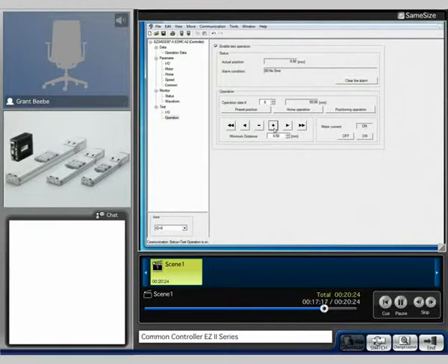By clicking the plus button, the table is going to move, or the actuator is going to move forward in the positive direction in increments of 0.5 millimeters. I can run continuously in the low speed, which again was set to 6 millimeters per second, or I can run continuously in the high speed, which was set to 100 millimeters per second.